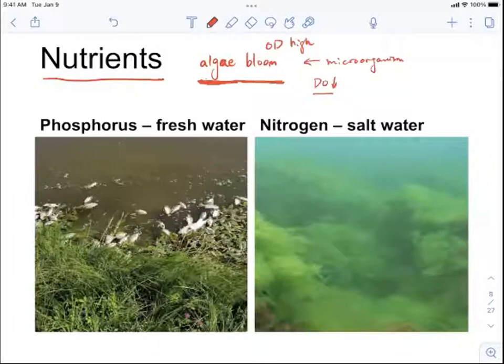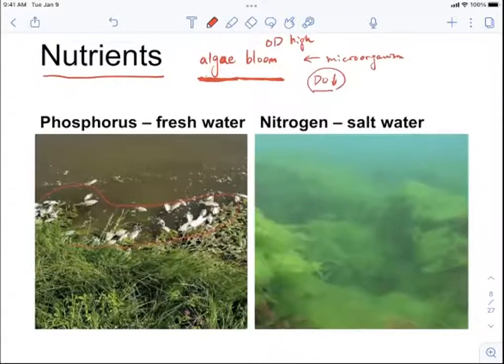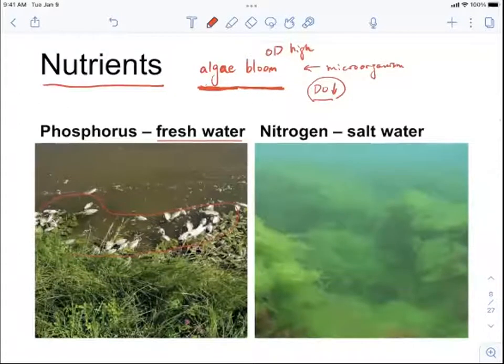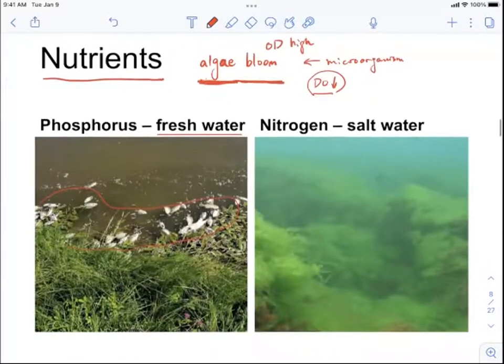And because of that, we have a lower oxygen concentration, and then the higher-level living species are going to die off, right? Typically, for fresh water, let's say the river water or lake water, phosphorus is the limiting nutrient. But by using more fertilizers from the farmlands, you may lead to these algae bloom scenarios, and then it's going to cause these problems. And for salt water, let's say the seawater, nitrogen is the limiting species, okay?